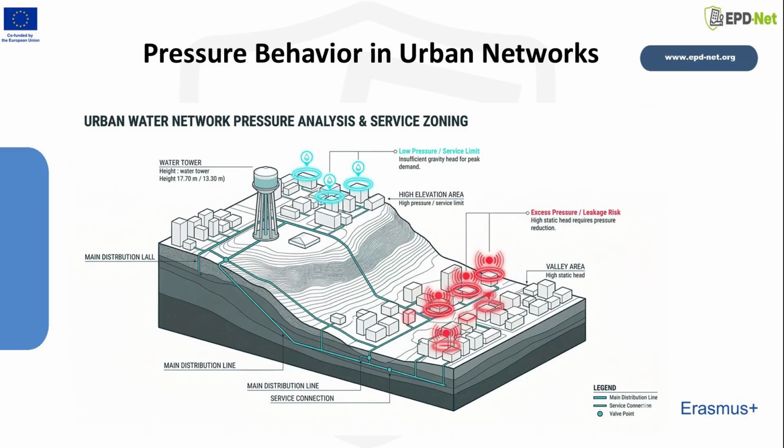Pressure also changes over time. Daily demand cycles, such as higher usage in the morning and evening, and seasonal variations, such as increased consumption during summer months, cause temporal fluctuations in pressure. Understanding these behaviors is essential for designing effective pressure management strategies.